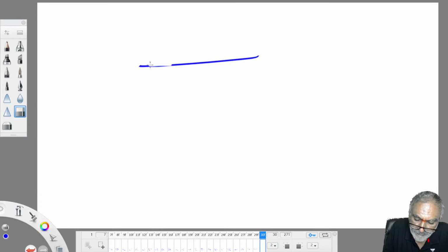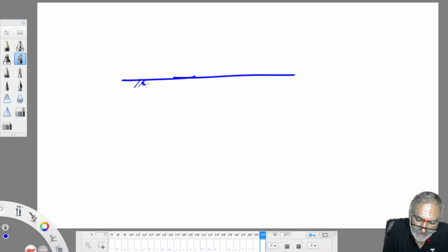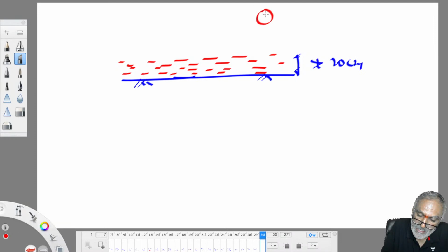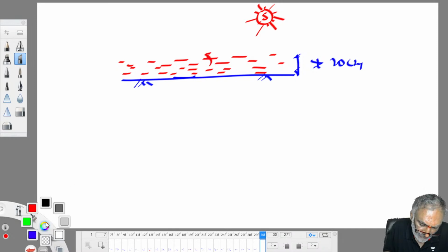This is open land. Open land means what? It straight away gets exposed to sun. This is a land, so we spread sewage effluents on the piece of land, open land like this. These are the effluents. Its thickness should not be more than 20 centimeter. So when this gets exposed to sun, what happens? Evaporation occurs, no? So most of the liquid evaporates.